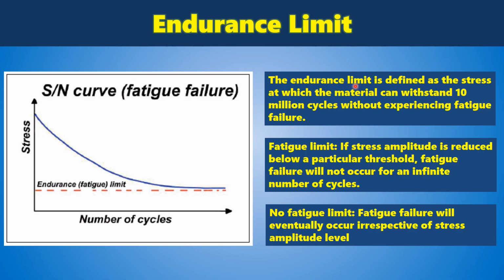And that's an arbitrary number used by the companies that manufacture orthopedic implants. They claim that the material can withstand 10 million cycles before it fails. And the material can, on an annual basis, withstand 1 million cycles. So at least the material that you are using can stay without failure for 10 years.